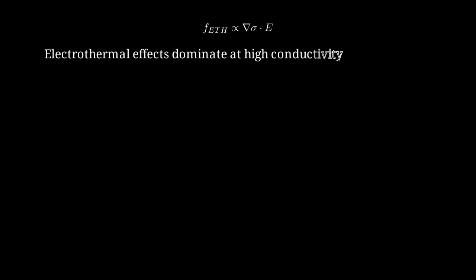Electrothermal flows become dominant in highly conductive fluids. In biological buffers with high salt concentration, electrothermal effects often overwhelm ACEO. This is a major challenge because biological applications require physiological salt levels.